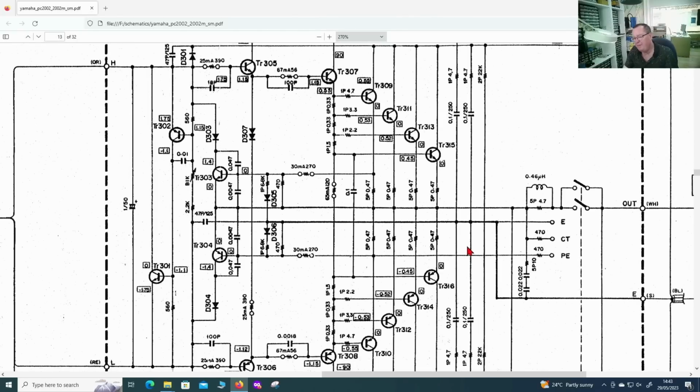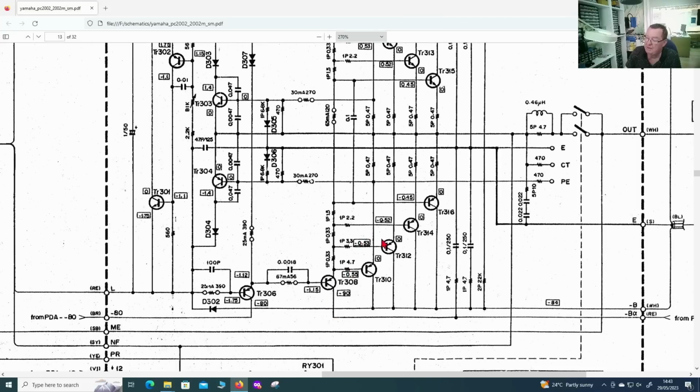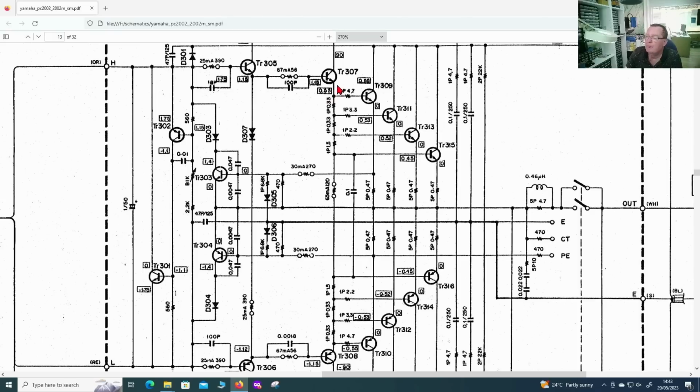One other thing I find very interesting about this amplifier, and so interesting I'm going to mention it. The driver is driving the 4 output transistors, and then we have resistors from the emitters to ground, and the same thing on the negative half of the amplifier. Okay, but look, we have a voltage here, 0.55 of a volt through the base resistor onto this transistor.